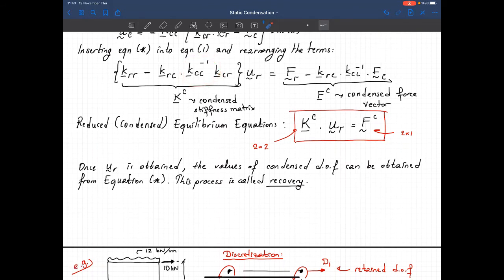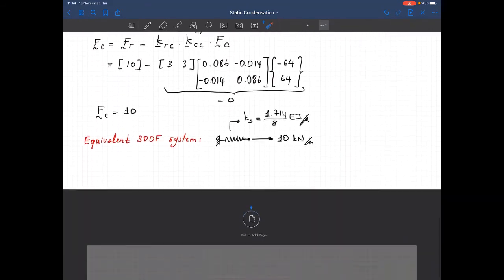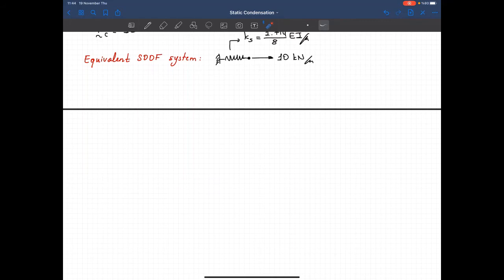So there's an alternative way, and the alternative way is very straightforward actually. We do incomplete static condensation, and from the incomplete static condensation we can obtain the equivalent stiffness matrix and equivalent nodal forces. So as an alternative approach, incomplete factorization, and I will show you how.